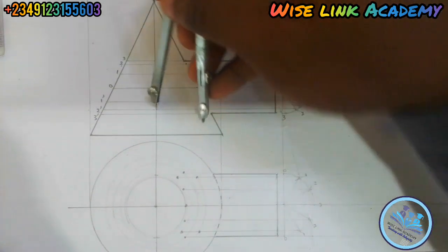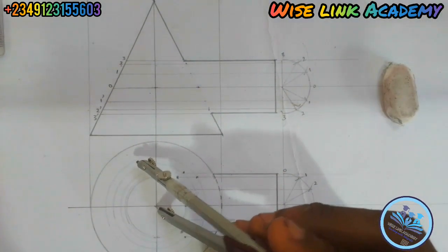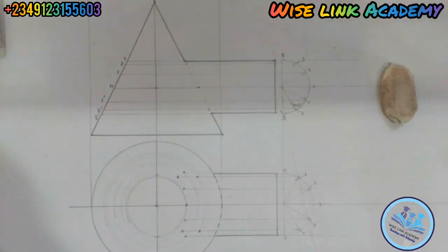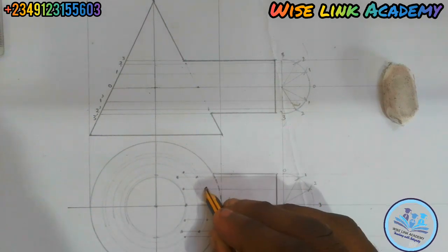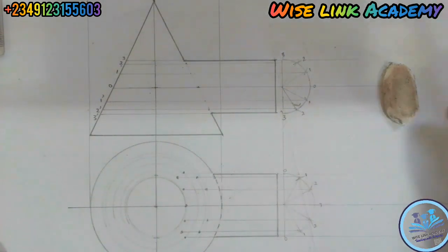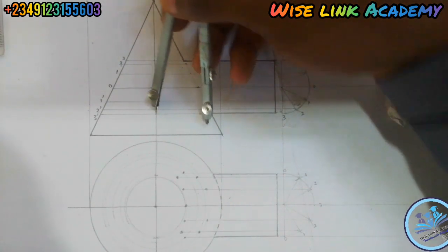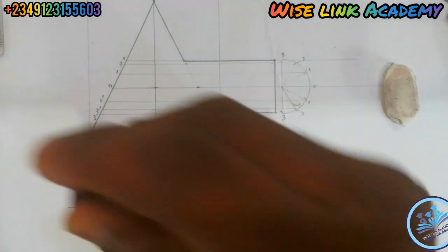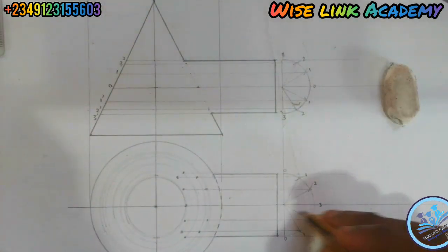Come to 2 prime. From here to here is my 2 prime. So take it to this center point and draw a circle this way. Now where 2 prime is meeting 2 at this point, as you can see. Next up, point 3 is the last one. Alright, I've done for 2. Then 3, from here to this point, is my point 3. Take the center point, draw a circle this way, then extend it. 3 is touching 3 at this point.